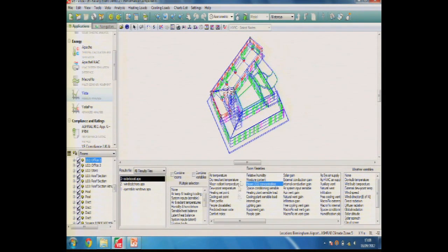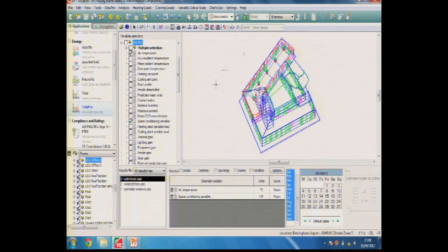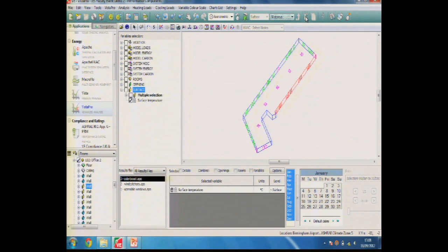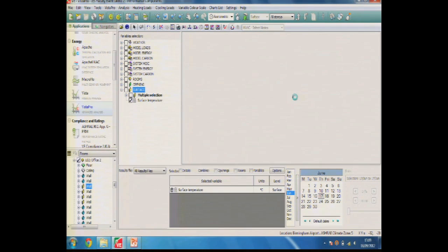Now there's various other elements that we can look to explore, but what I'm going to do now is just show you in Vista Pro quickly a bit of bulk airflow analysis, which relates back to the explanation of the Windcatcher's operation, which I spoke about before. Here, if I just click on System. So what I've done is I've just gone down to zone level here, so we're focusing on the 4 quadrants of that Windcatcher, which are entering the zone in which the Windcatchers are serving. So if I just look at the bulk airflow analysis here,